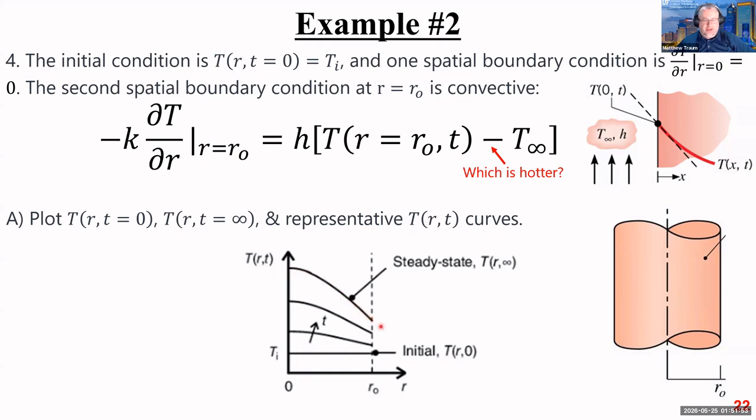And when we get to the edge, we've got some constant value of the slope, right? dT/dr is some constant value. So you can see that here in the convective boundary condition, that's the word I'm looking for. So this guy, because the air is colder than the copper wire, is sloping downwards, but that slope is constant once that spot hits the edge of the wire.